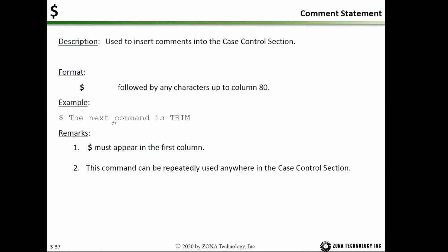And in the entire ZONAIR input file, if you specify a $ in the first column, that means this is a comment, and ZONAIR will not read this line, so $ must appear in the first column. Okay, this is the end of section 3.